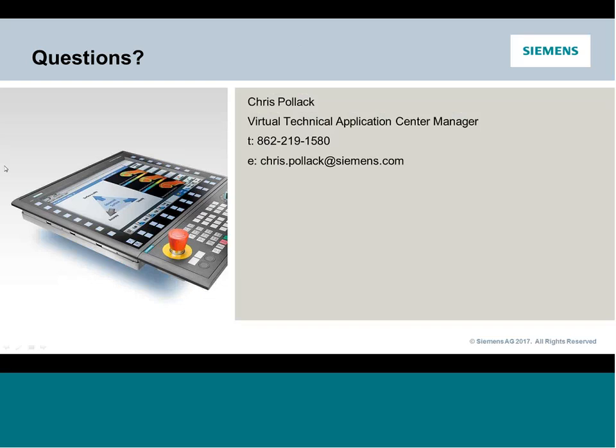So we did get a question from Gary. I use the Siemens control on a bloom grinder. Is the part programming part the same? So, you know, I'll have to apologize, Gary. I don't get the opportunity to get on very many grinders. The other tricky part with the grinders is a lot of those OEMs do custom front ends. Now, what I will say is the core cycles are the same. They are available there. Whether or not you can get to them from the interfaces easily, I'm not sure. That would be something we'd have to explore a little bit.